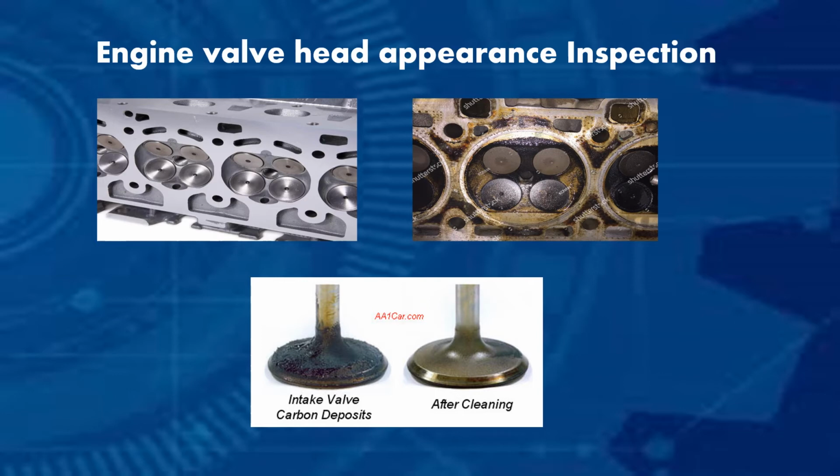If fuel no longer passes over and washes the back of the intake valves, carbon deposits commonly form on the valve surfaces. This buildup affects the way air enters the combustion chamber, causing many symptoms including, but not limited to, misfiring, rough running, hard starting, and poor fuel economy. Worse yet, the likelihood of a burnt valve, a form of major internal engine damage, is drastically increased.